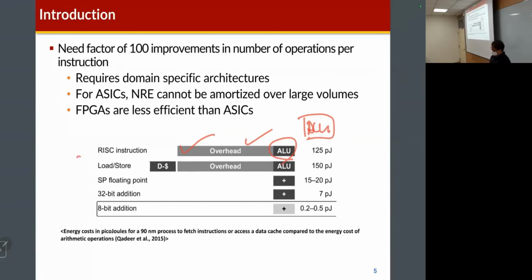And then if a load store instruction is required, then we also need to access the cache. So the memory also consumes actual power, because the memory size is very large compared to the execution units. Also, the size matters for power consumption recently. For the older generation processors, dynamic power dominated the total power consumption, but recently static power dominates.